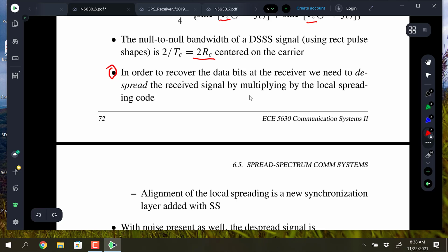So a big important thing with spread spectrum is that in order to recover the data bits, you have to despread. And the code pattern is generally very, very long, so that even if you think you knew a piece of the spreading code, the code might not repeat for days or months, a very, very long time. So finding the proper alignment in that is non-trivial. And in second generation cellular that used code division multiple access, every cell phone that does CDMA, and my cell phone still does CDMA, I believe, has that standard still supported for situations where a cell site might have it.